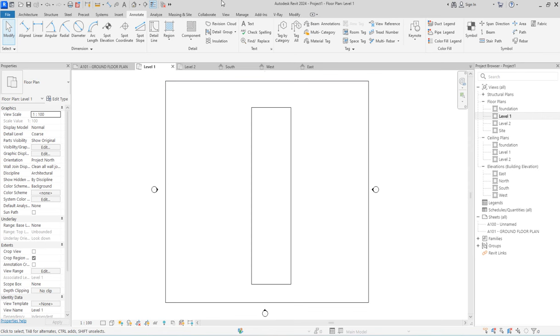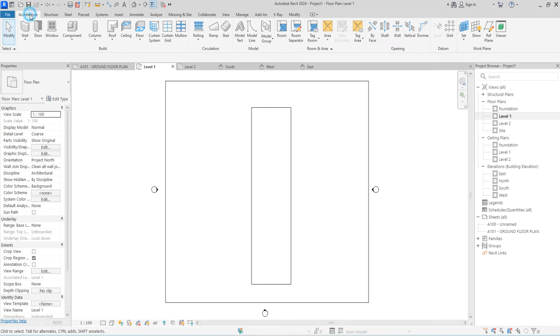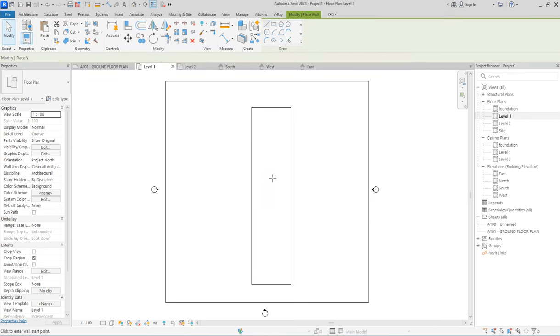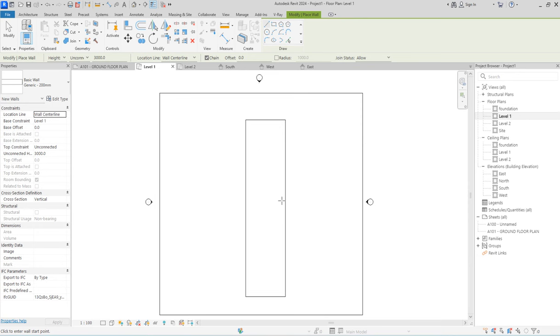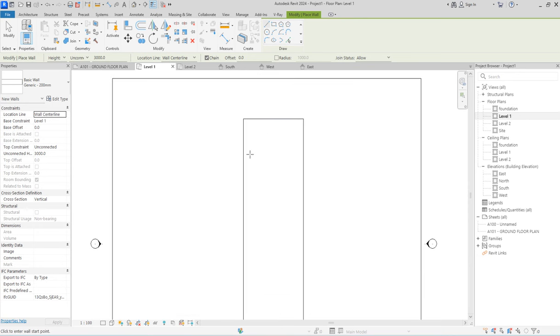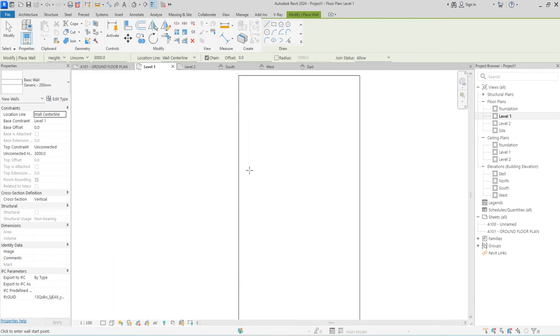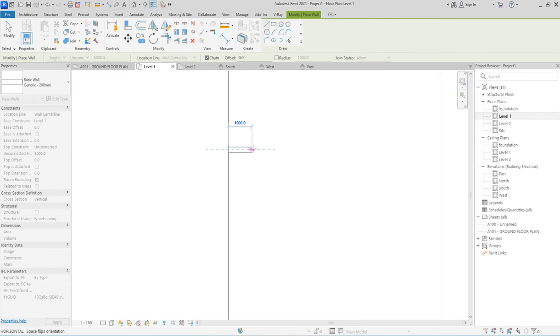Let's move. So this is the guide for that particular. Before then I will later draw my property line. But let us go to the main building and start doing something that is necessary. The first thing you need to do is to get the setback from the wall. Because this is not a complete plot of land, the setback according to the rules is just like 1 meter, 1.2 meter.